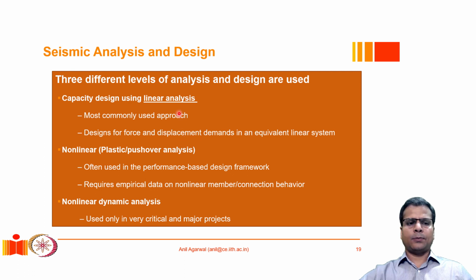In this approach, the advantage is that it is a simpler approach. It does not require so much computational power because the analysis is all linear, and we do not need very accurate constitutive relationships and connection behavior, etc. Whatever models are easily available for connections can be utilized because the analysis in general remains elastic.